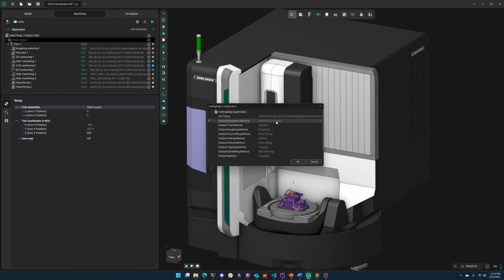So my default workpiece material is aluminium, and my default tool material is carbide. And this one is a bit interesting because there really isn't a tool material selection inside of ENCY currently. So what we do is we set a default, and if you remember from the web UI, we have these slugs. So if the description of a tool contains a slug, then it's automatically going to say that, okay, we saw HSS in there, so this is going to be an HSS tool. And this is then going to change the feeds and speeds completely, of course.